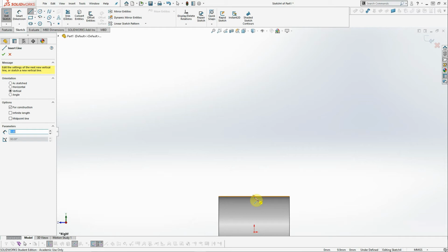This is how SolidWorks knows that one point is perfectly aligned with another point. And that's important because you want your figures to be closed. In order to extrude them, you have to have a closed figure. And if they're not, they might be off by a fraction of a millimeter and you won't see it. Which is why it's real important you wait for that point to get highlighted before you click.